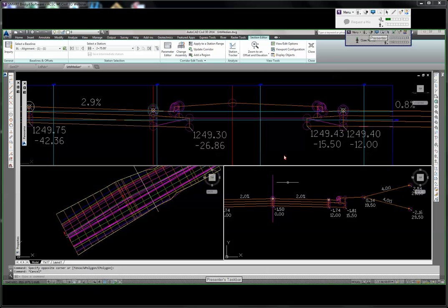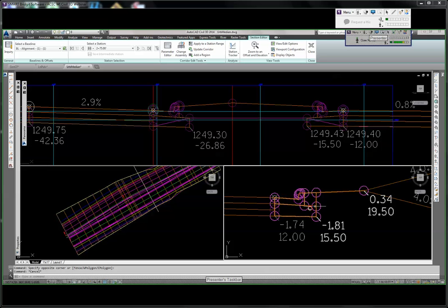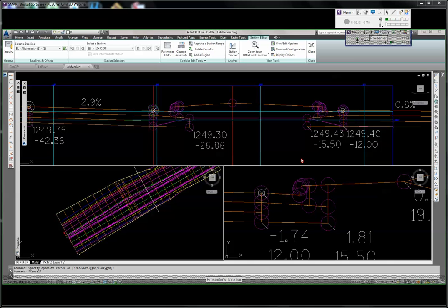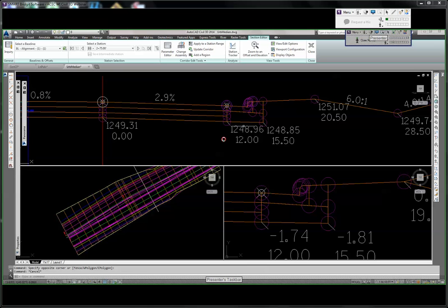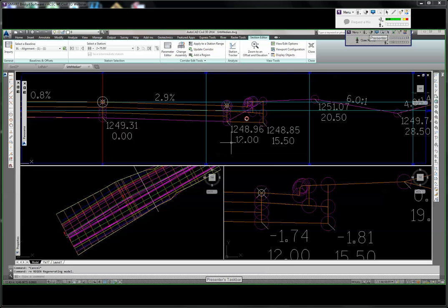Okay. Now that in turn leads us to talk about subassemblies that need slight consistent adjustments. These are things that if I use the urban curb and gutter, or I'm sorry, the CG Gen subassembly, generally I will always need to think of this one factor or go in and fix this in one field or such. The subassembly itself is fine, but you will notice that the,